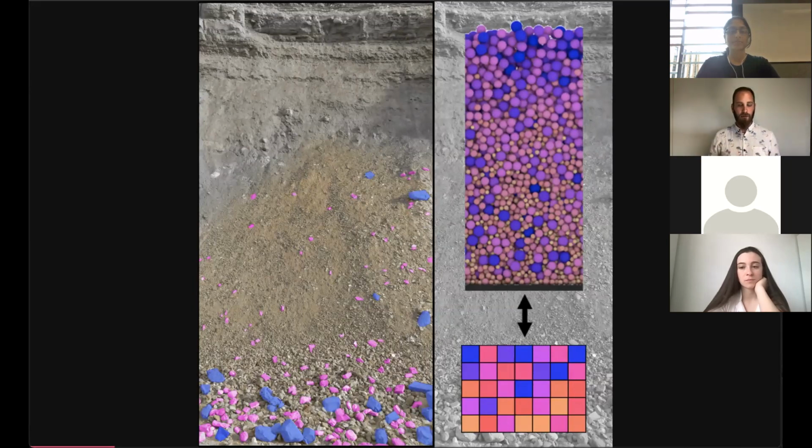And there's two simple-ish ways we can do that. The one on the top right, that's what we typically refer to as a discrete element method simulation. So we actually represent every individual particle in the flow, either as a sphere or some kind of shape. We let them hit each other, bounce off, and we simulate directly the whole flow. For a smallish system with millions of particles, that's kind of a feasible thing to do. For a large system with many, many more particles, that becomes less and less feasible to do very, very quickly.